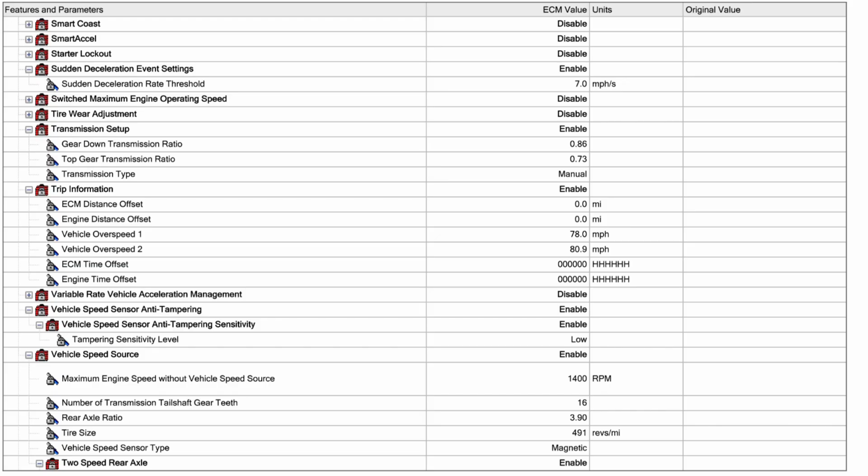Well, in the old days, 20, 25 years ago, after the ECM saw that you drove for 60 minutes, and that's what I was told was the magic number back then. This is actually an N14 Select Plus. 60 minutes, the ECM would lock out to 5 miles an hour because they believed it was tampered with. And the only way to fix that is it had to get towed to where there was Insite, and you had to recalibrate the ECM to drive that out.